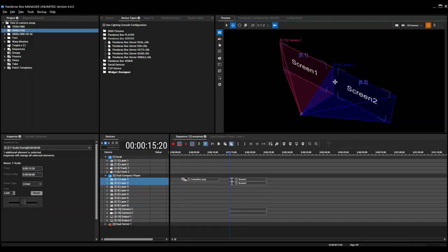And now it comes to 16 units, because Pandoras Box Render Engine always relies on 16 units to fit the first connected monitor device. So mostly the local monitor on the manager, if you use a manager scenario, will set 16 units to the size of the monitor.